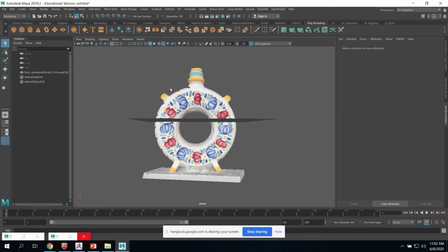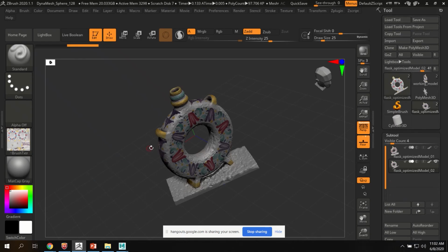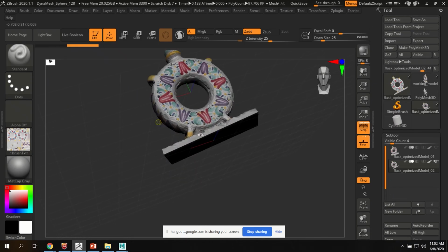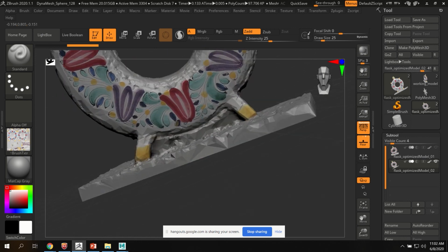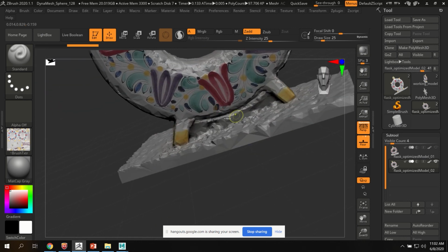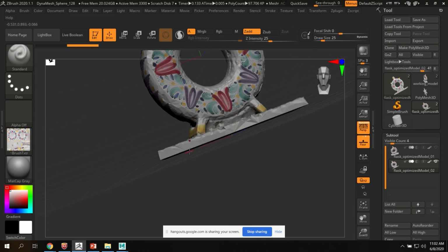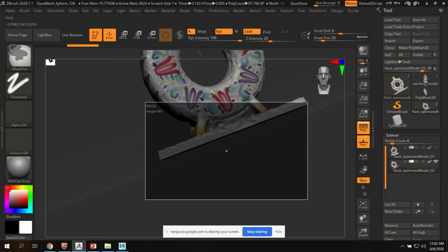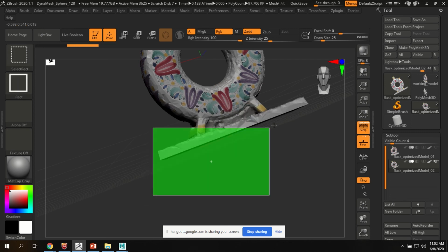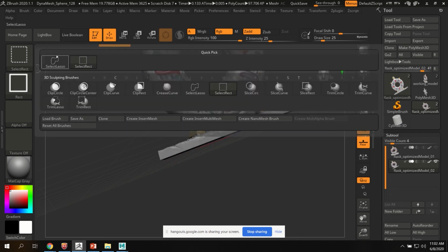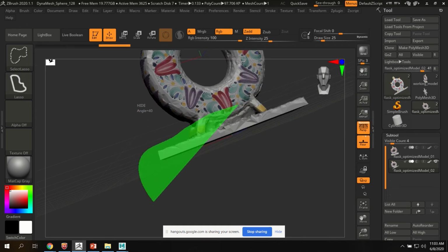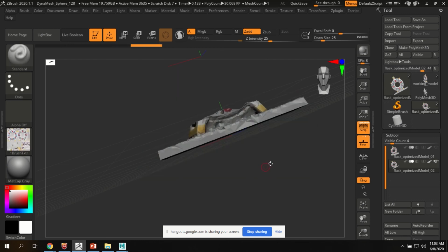Yes, the best way to fill that hole would be fill hole. There is another function in ZBrush where you can fill holes. It's a little bit longer and sort of finicky. I can go over that real quick. There's a tool called ZModeler. So I'm going to actually create a hole and show you. I'm going to hold Control Shift and slice the bottom on purpose like that.